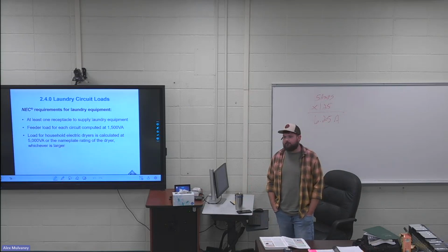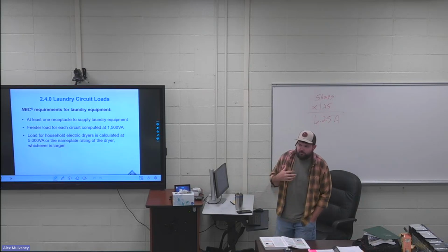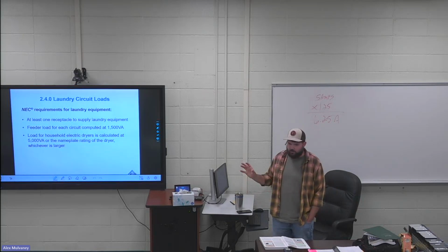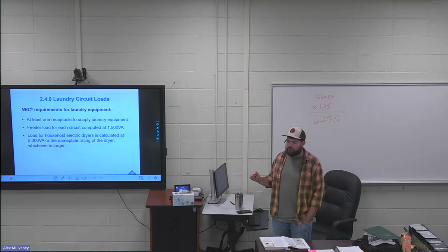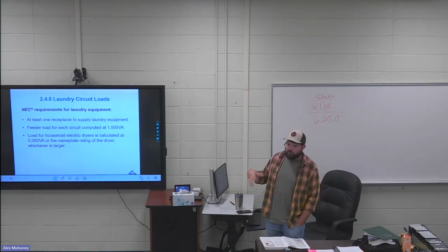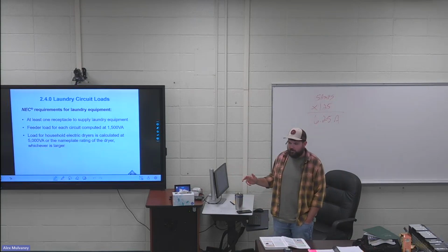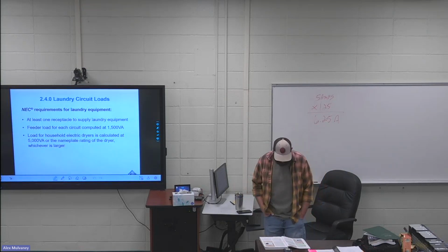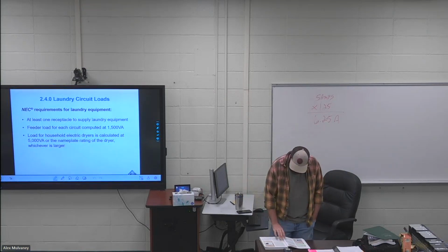But say somebody, and usually, whenever you're an electrician installing this stuff, you're putting in the dryer plug, unless something is specified, hey, we're gonna put in this gigantic dryer and it runs on 10,000 watts, you're gonna have to put a specialty circuit in for that, right? Most of the time when they're sizing out houses, they're saying their dryer's gonna be less than 5,000 and then size it for that.